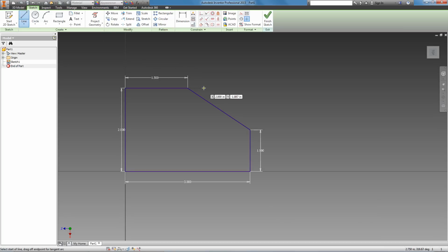It doesn't really matter because once you create a sketch and then extrude it, your sketches disappear, but not permanently. I'll show you how to fix that. You saw what I did there? I came down, lined it up with that line, and went over. I'll show you again. Down, come over, whoa, and then boom.